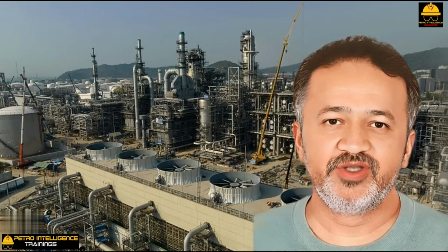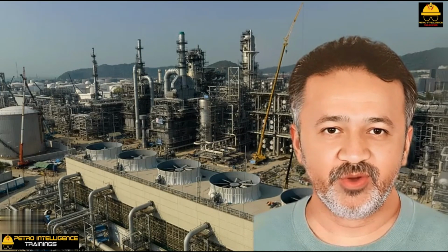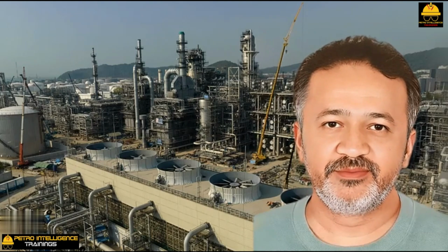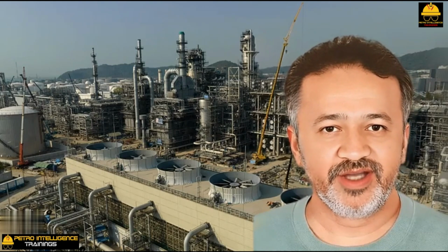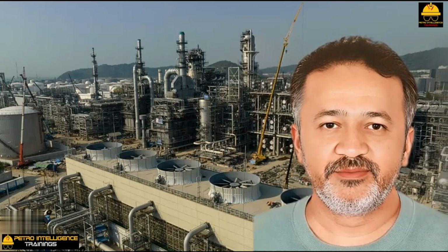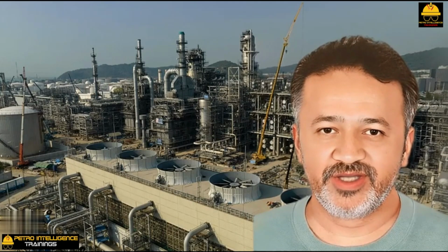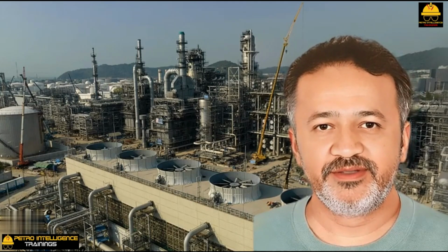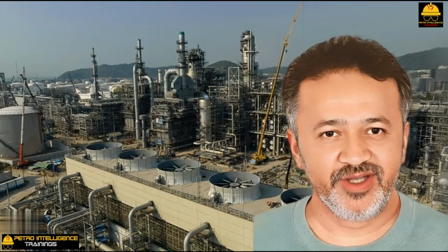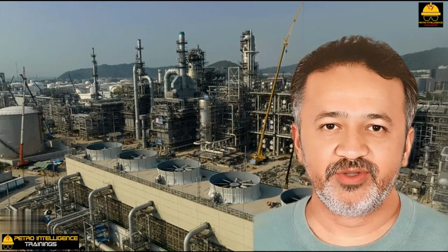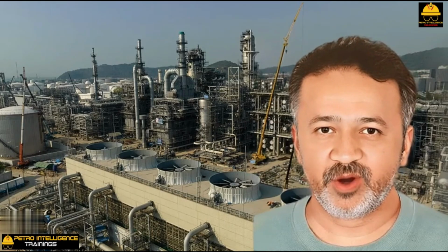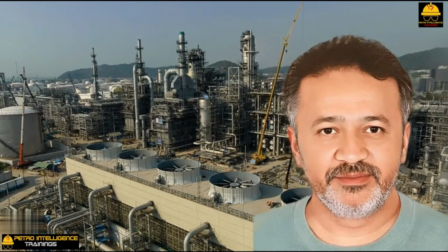Fin deterioration. The fins are usually made from aluminum. Especially in moist, steamy environments, the fins are subject to destruction by corrosion. A corroded fin retards rather than promotes heat transfer. It's easy to break such fins off by hand. A high-pressure jet of water can be used to knock off the corroded fins and partly restore cooling capacity.